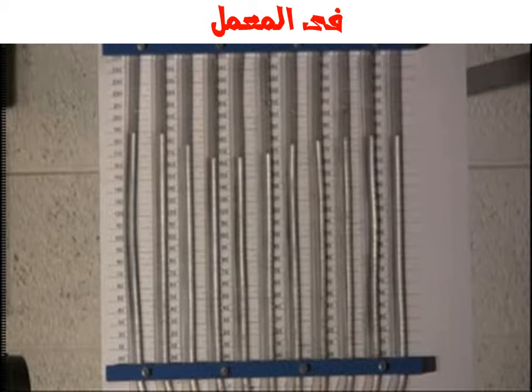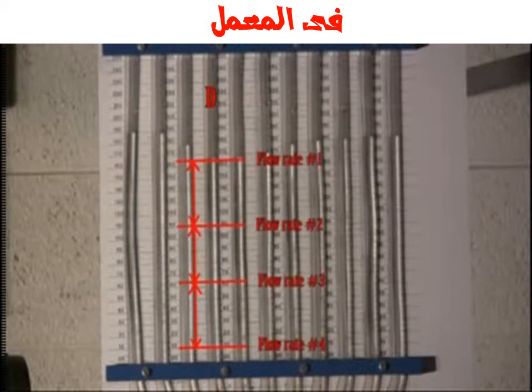Next, we will determine the intermediate flows. First, determine the difference between the two extreme readings for piezometer D. Then divide this difference by 3 in order to roughly determine the interval between the two intermediate piezometer readings at station D between the maximum and minimum flows. Record the piezometric head in all piezometers for this minimum flow from left to right.